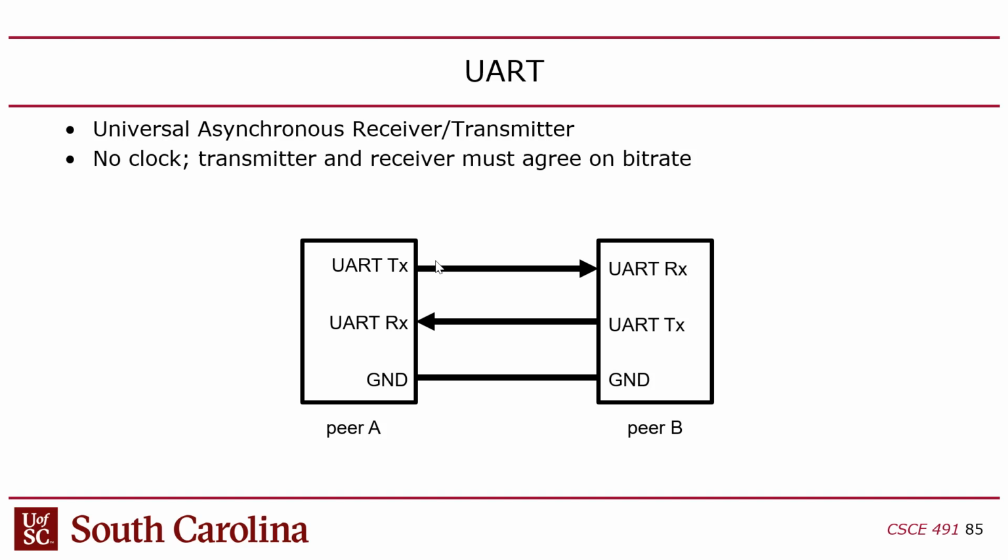But there's no clock. So it's asynchronous. It's an asynchronous protocol. And there's no slave select. So how do you know when a transaction starts? The way it handles that, it uses start bits and stop bits, right?